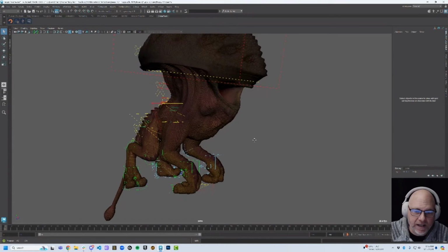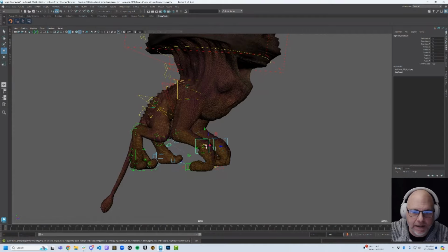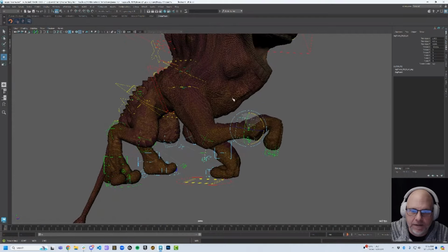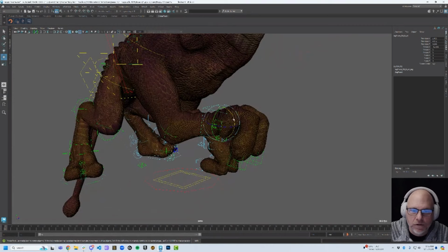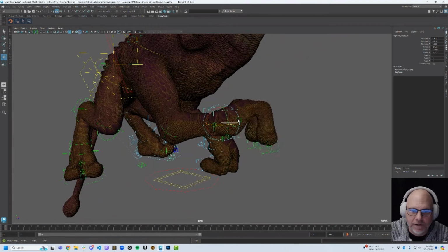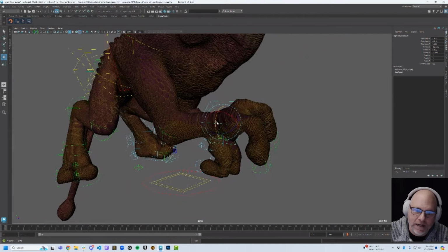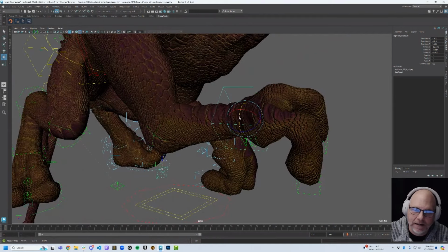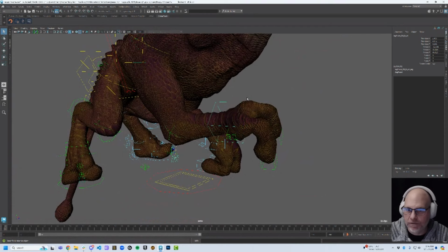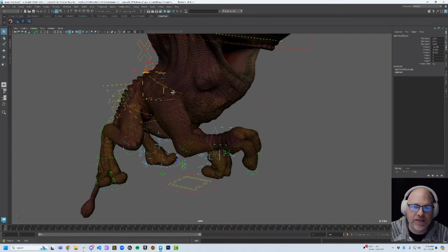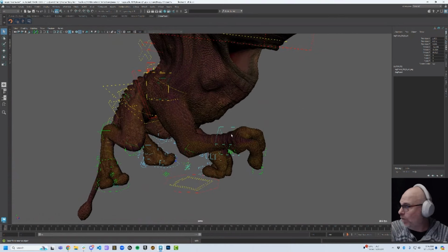So if we think about, just generally speaking, when I bring this up here, a wrist, right? You have your up and down, you have your left and right, but when you twist it, the weighting is averaging down the arm, right? Now, in a traditional Maya way, or any joint system, you have a joint right at the wrist, and you have a second joint right behind it, and one, if not two joints down the arm, right? Because you're averaging your twist out. So that means a system like this, it's not 3 joints, it could be 6, 9, 12, right? You've got all these extra rigging structure under the hood to try to get the surface the way you want.